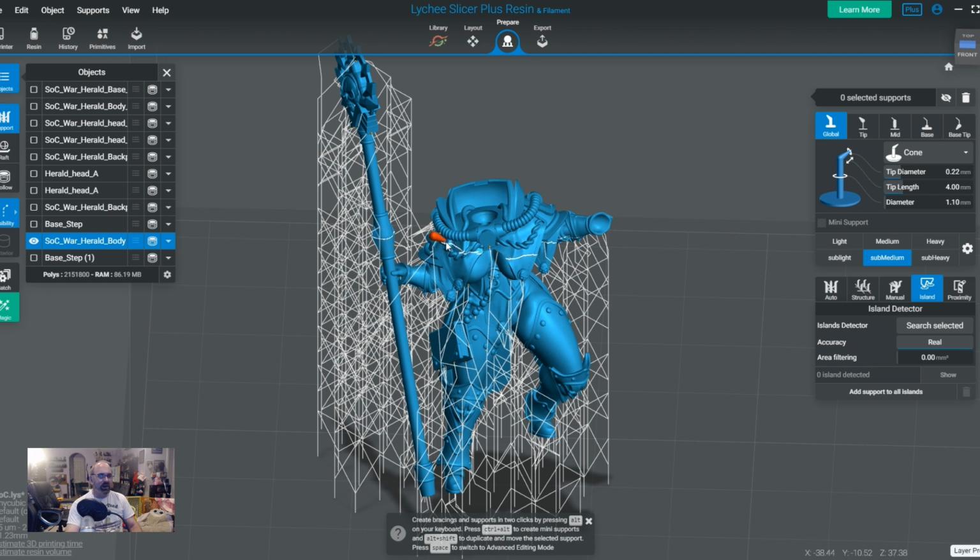It's not that it's going to create warping or anything like that. In some cases, it'll just create failures. It might just pull it off because it's just too much force. It might not, though. It might not have any effect on it at all. It really just depends on how big the cavity is and how much force that's going to have, size of the printer, all that kind of weighs into making a difference. But do keep that in mind when you take a look or set up and orient a file. It's definitely something to consider.